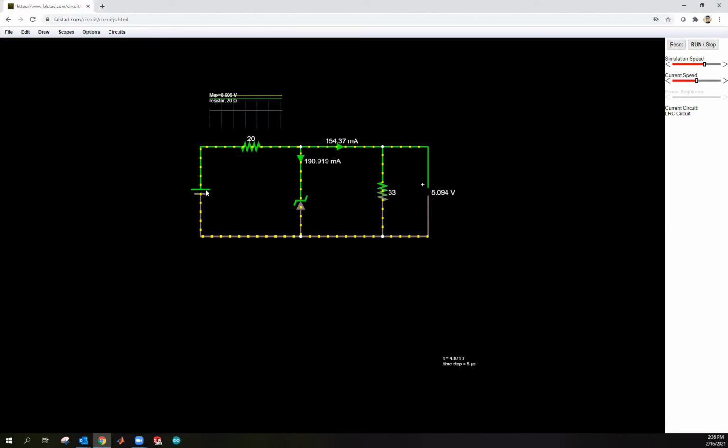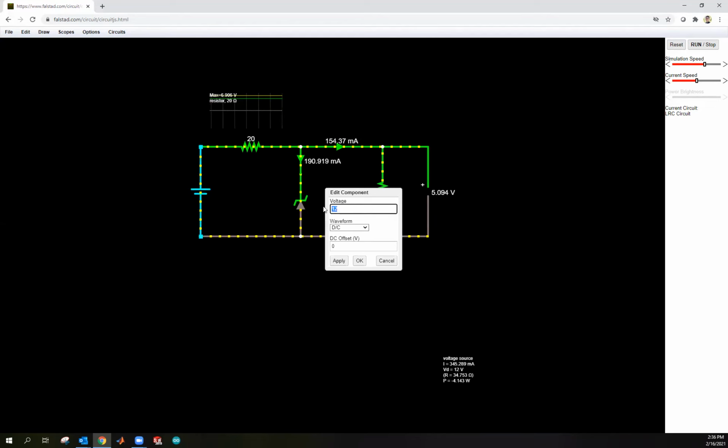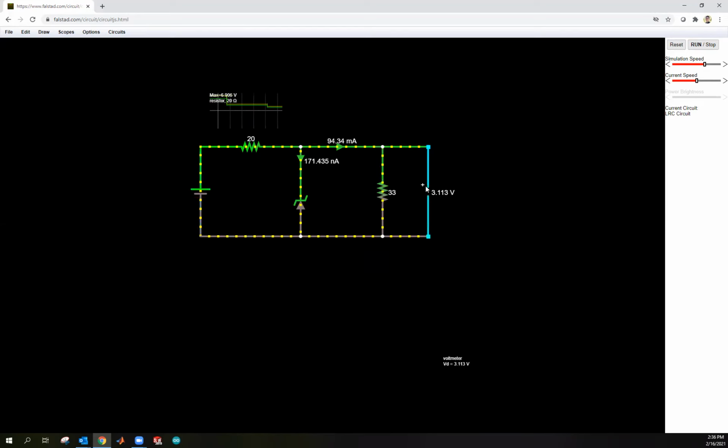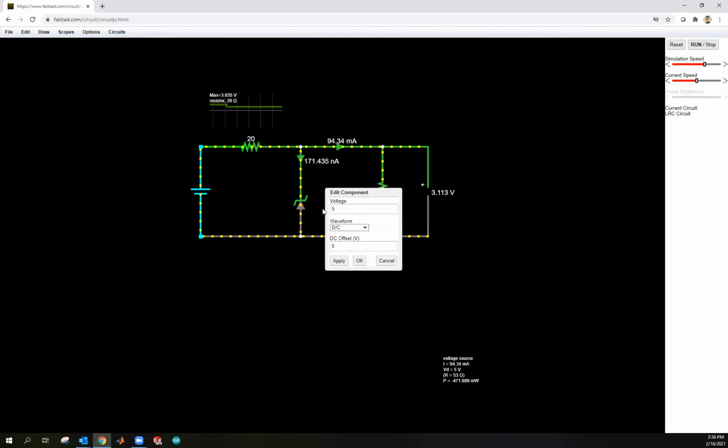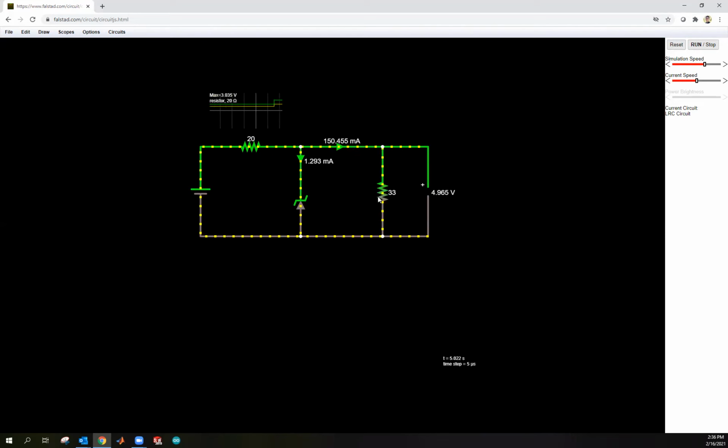But now let's say I go to 8 volts here. Actually, let's go even worse. Let's go to 5 volts. Look what happens. The voltage drooped, so you can see how this is not designed to operate below that regime. Good. So let's go back to 8 volts. We're just at the limit.